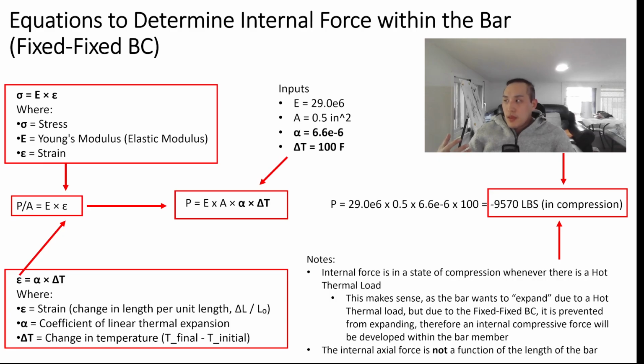But in this idealized problem statement, you can determine the bar forces by simple mechanics of materials equations. So as you can see here, we have stress equals E times epsilon, stress equals E times strain. And then when you decompose that, that's P over A equals E times epsilon.